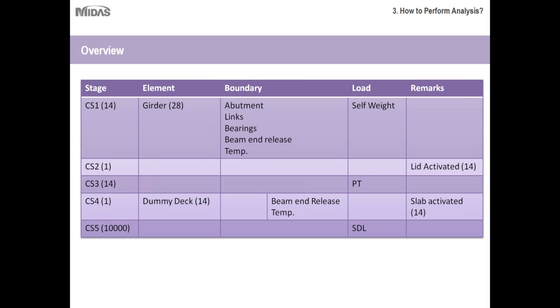I have not modeled the weight of wet concrete on the structure. I agree this is important. So you can consider the weight of wet concrete applied in this stage. And in the following stage, we have activated the members that represent the deck on top of the girders. And it is at this stage we'll remove the temporary supports in the beam and releases that were there to simulate the splice connection and the shoring members.